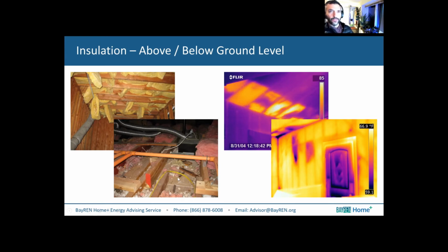Lots of debris, people get roofs redone. They have workers go up there, contractors, they move stuff around. This is why blow-in insulation is so forgiving. Contractors might say, well, bad insulation is better, but scientifically it's not. It buckles, it allows air gaps to exist. It's not rodent friendly, or maybe it is, they like to nest in it more. Cellulose is borate treated, with better fire ratings, and even loose fill fiberglass has much better ratings and is more effective.